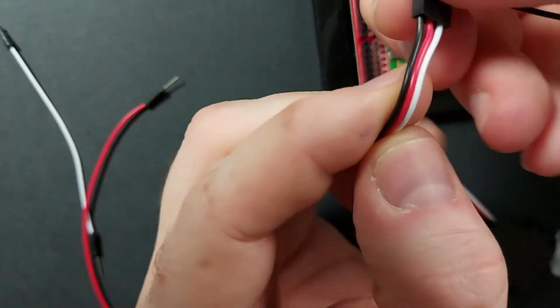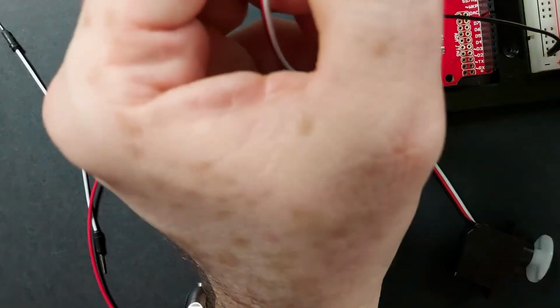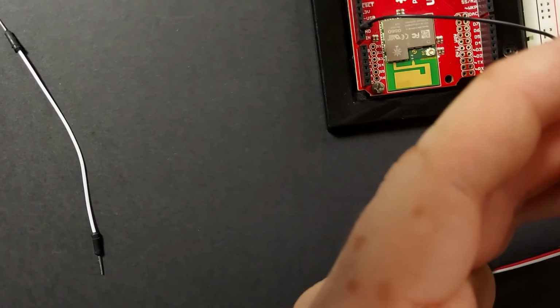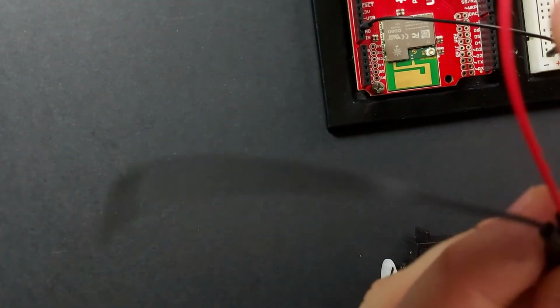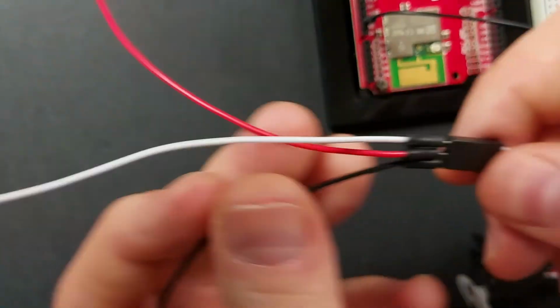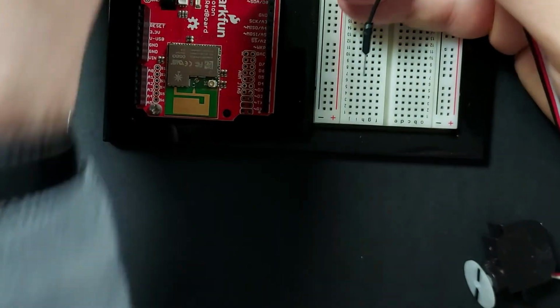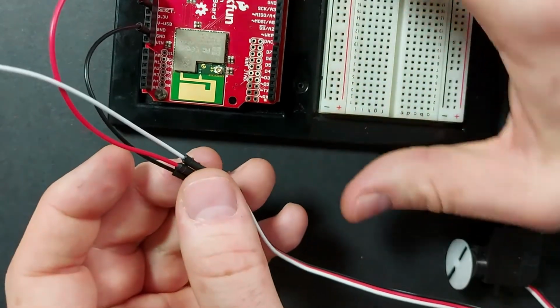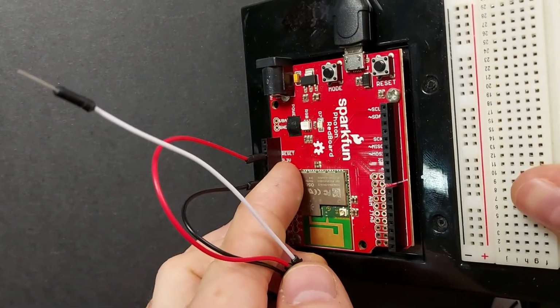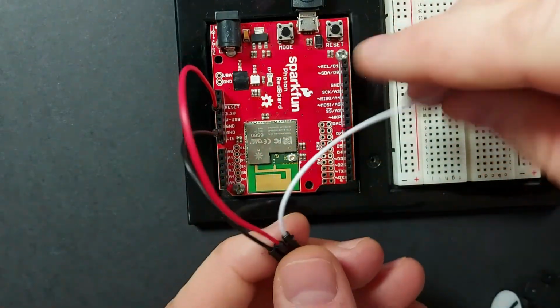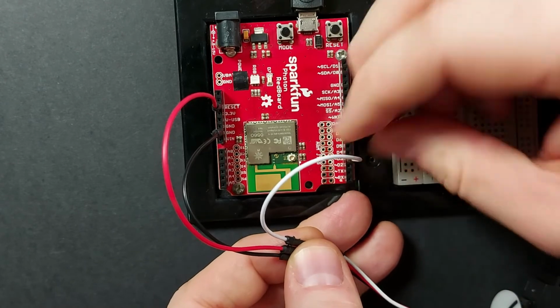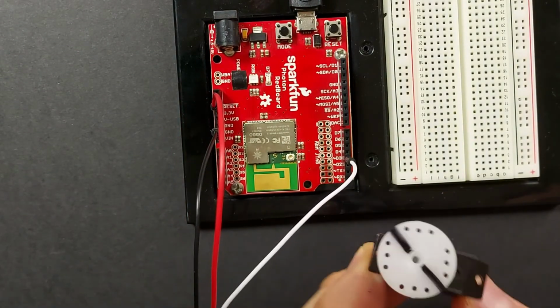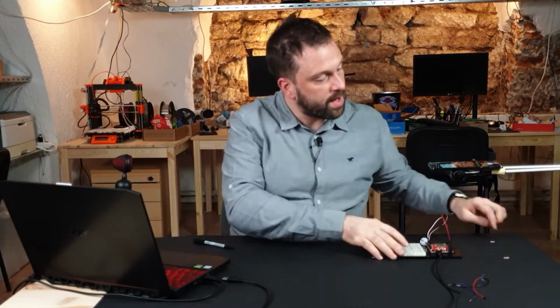See here, the black color is for the ground. I need some red here for the power source, so it's on 3.3, and the white one is the data. I'm using this kind of wires because I don't have any convenient connector here, so I'm gonna connect this to the ground. So this one goes to the ground, the red one goes to the 3.3. Be careful not to put it in USB, just 3.3. And the white one, we will put on D3 here, and this is the servo. I put some cap on it so you can see the motion, hopefully, if this will work.